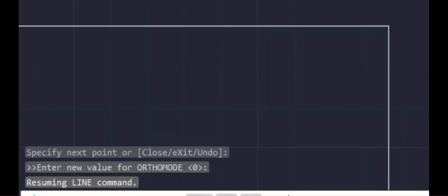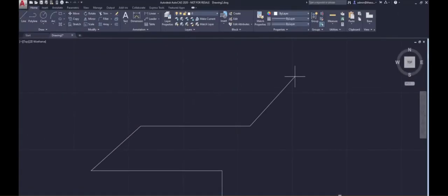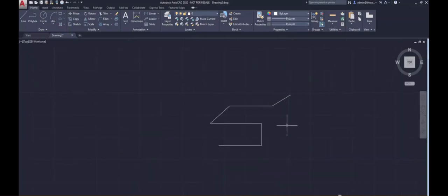add the angle sign. Now type in 30 and press enter, and AutoCAD will now take this value as angle, not as distance. So if you move your cursor now, you're going to see angle override here, which is now set to 30 units. So if you now move your cursor, the length will change here, but not the angle. So all you need to do is now type in the length. So maybe I'll type 50, enter, and here it is. So now the length of this line is 50 and it is inclined to an angle of 30 degrees with respect to positive side of x-axis. Now to exit the command, press enter key. And this was the line tool.